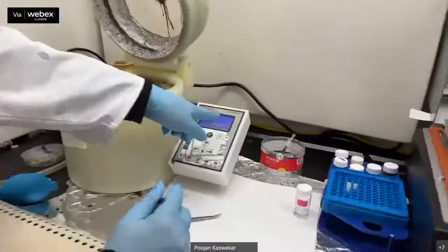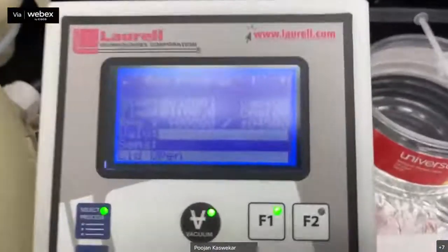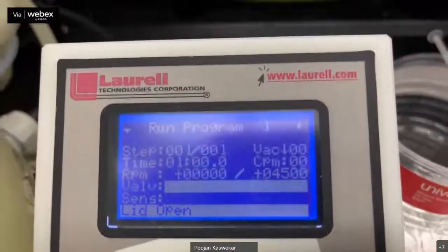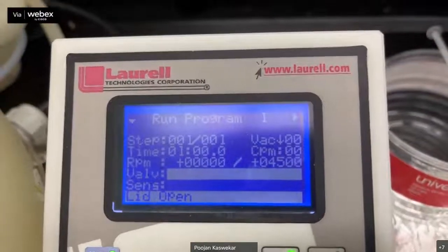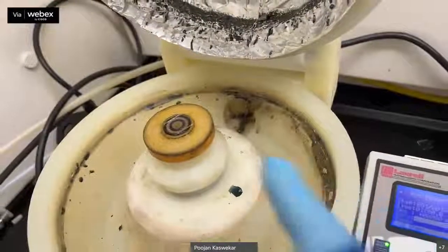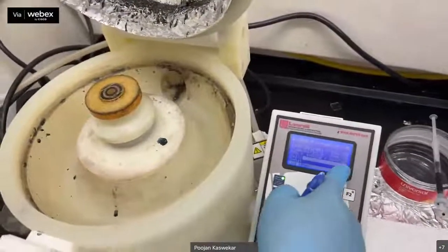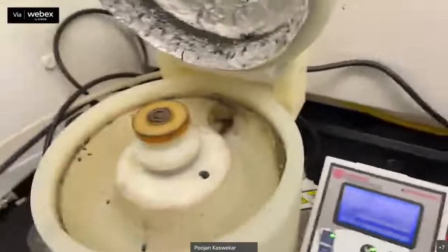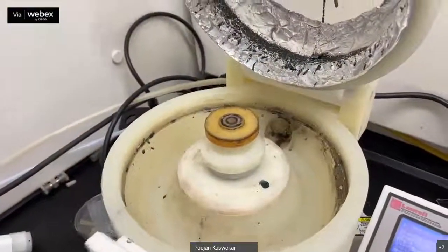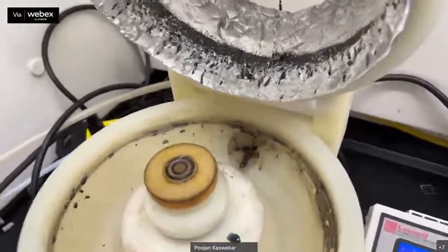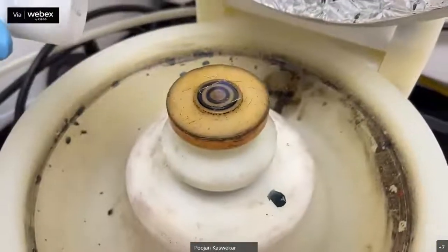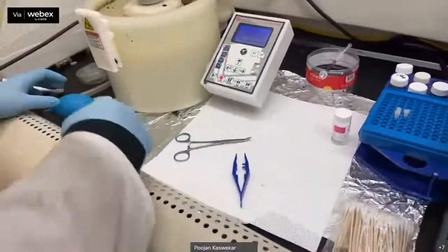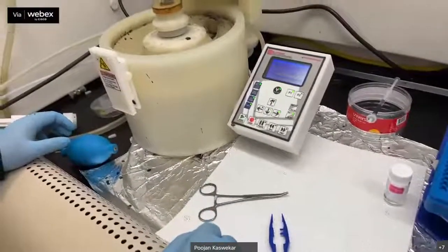So you can see if this number changes. If we set 0, it means there's no vacuum and you can adjust. If you press it again, the number changes, which means the sample is still on top of the spin coater. Then you can blow away the liquid. There is a final blow just to remove any particles from the substrate.